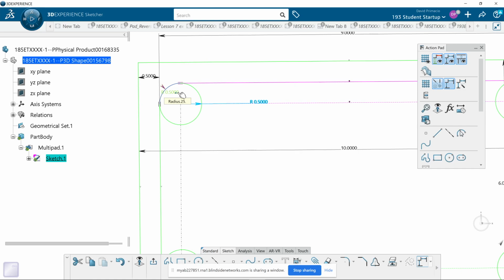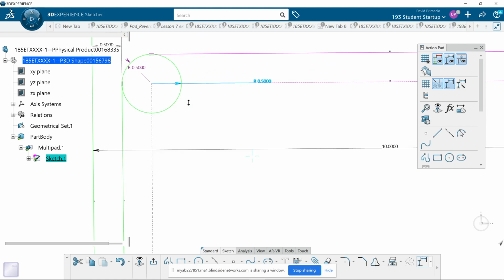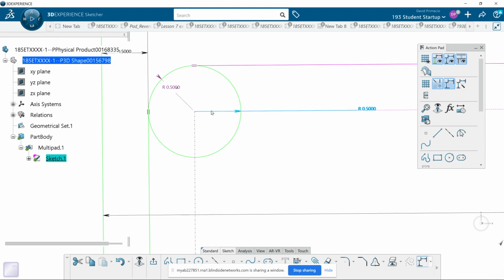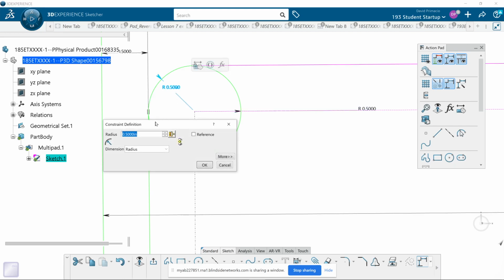So you can use that. It's still within engineering spec. Yes, if I change it to 0.53, it's still within engineering specs. I've machined it according to the engineering drawing. It could be up to 0.53, and I'm able to use my 1/2 inch cutter. Because by changing that to 0.53, what will happen to my tool path right here? It can maintain tangency, and efficiency.